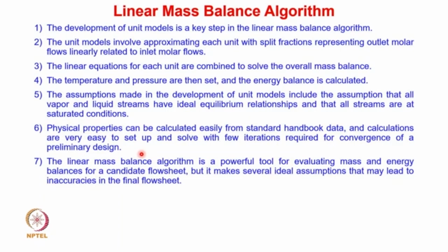So the development of unit models is a key step in the linear mass balance algorithm. Because of that, we have formulated the linear mass balance equations for different units. Then the unit models involve approximating each unit with split fractions representing the outlet molar flows linearly related to the inlet molar flows. The linear equations for each unit are combined to solve overall mass balance. The temperature and pressure are then set and the energy balance is calculated.